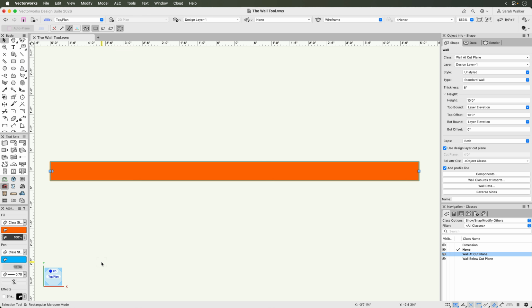Another way to have the attributes controlled by the wall as opposed to the components is to use detail levels. Detail levels can be set in viewports, and if you set the viewport to low detail, you will see the wall attributes as opposed to the component attributes.